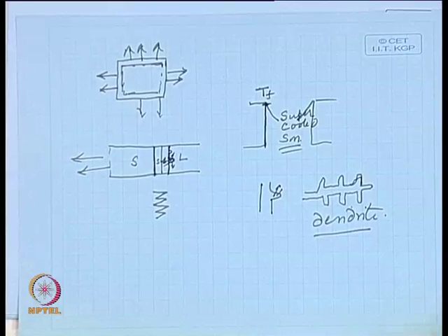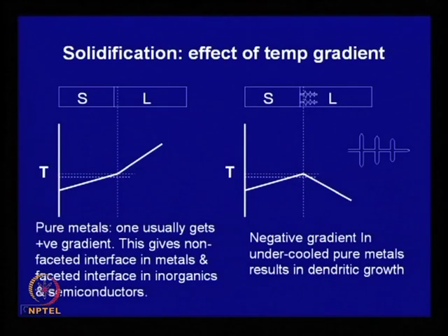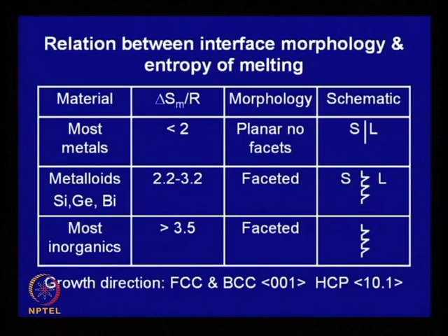This type of shape of the primary crystal is also possible, and all this is determined by the thermodynamic characteristics of the material, and there are certain correlations people have found. Looking at the thermodynamic database, there is a correlation with entropy change, entropy over R, a dimensionless number.